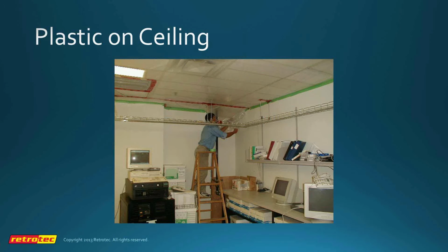So in this case, we're covering the ceiling in plastic, and even though I've tested 300 or 400 rooms in my lifetime, I've only done this 4 times. And when you do it, you realize that it's time-consuming and fairly inefficient. Moreover, if you happen to fail, then you've got to pull it down to fix it and then do it again. For a 500 square foot room, it takes roughly about 4 hours to do this properly.